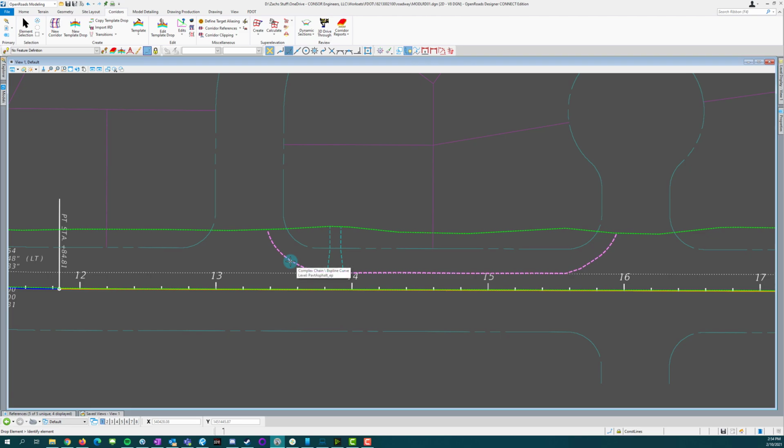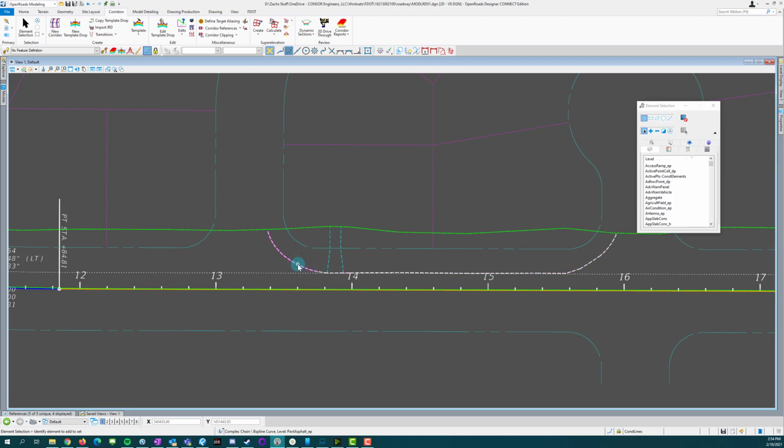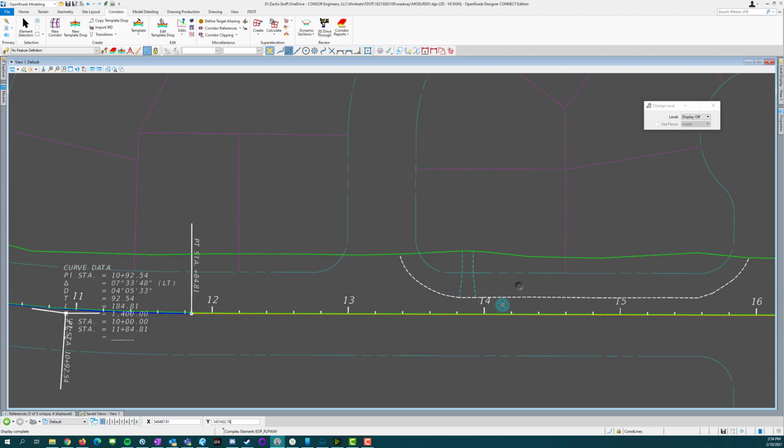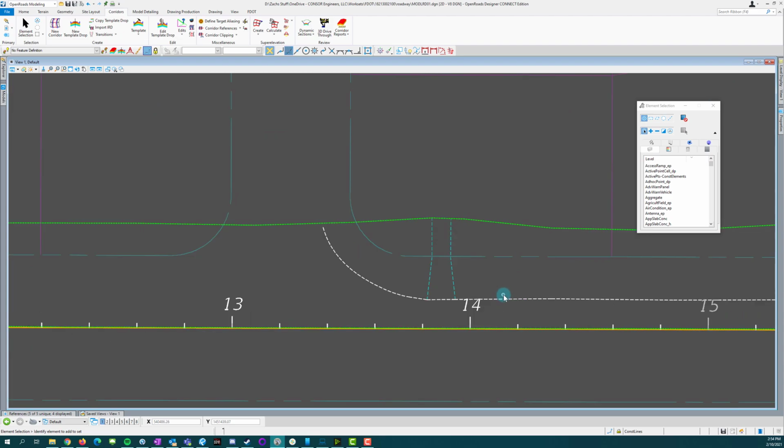I've got my drop tool here. Stuff's coming off the screen. So I'm going to try and drop this into its geometry. Another thing this does a lot of times is with this B-spline. These are curves, and I don't typically like making those into complex elements, so I like having lines and arcs. Let's see, what is this? Turn this construction line off. This looks like an extra line that was sitting in here.